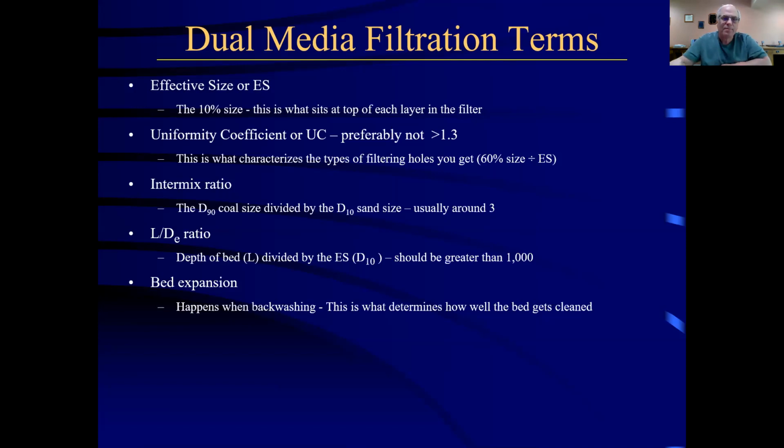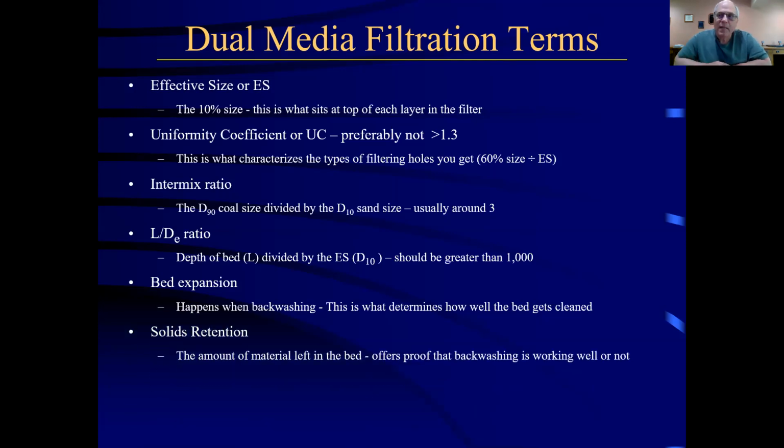Solids retention, that's the amount of solids that are retained in each layer of the bed as you go down through, usually every 6-inch depth layer. You want to take that out and you want to measure it, and we'll show in a second video, a more advanced video, how to actually go out and measure solids retention. But basically, when you backwash the bed, you want some solids to be retained in the bed. That's filter ripening. We don't want to wash away all of our ripening, because if we do, we have to re-ripen the bed. And if we don't have filter to waste, that's going to be a problem for us. So solids retention is a very important key topic.